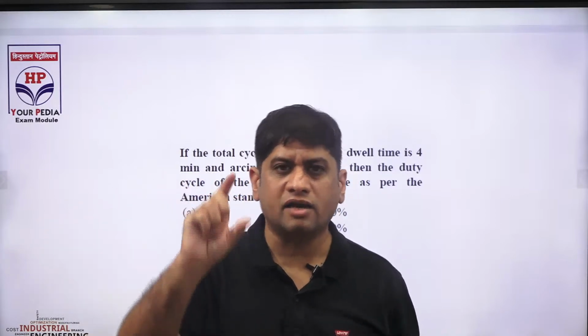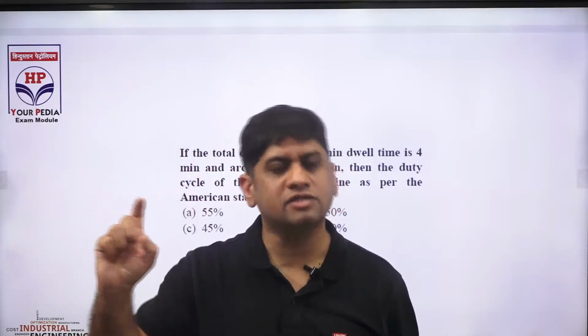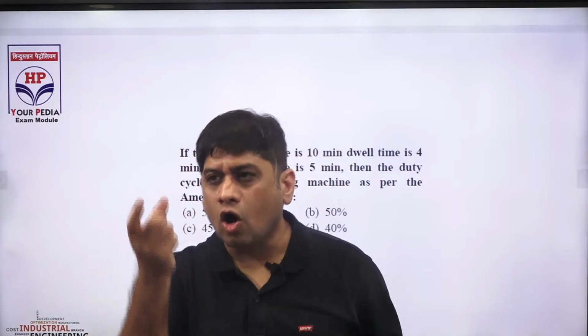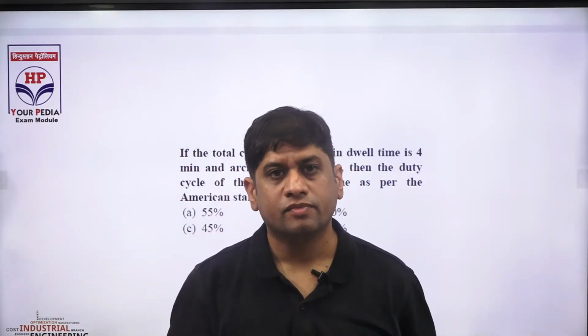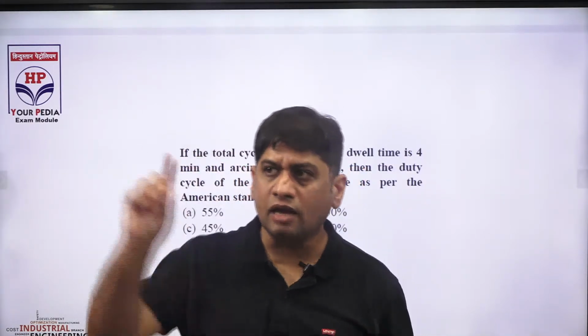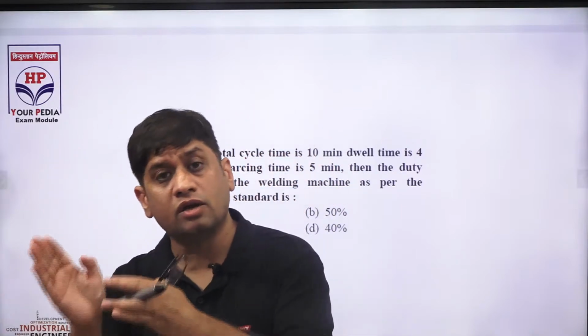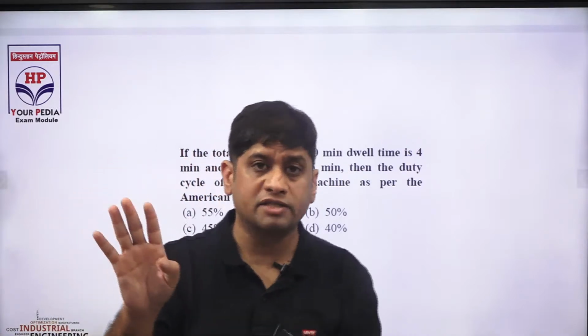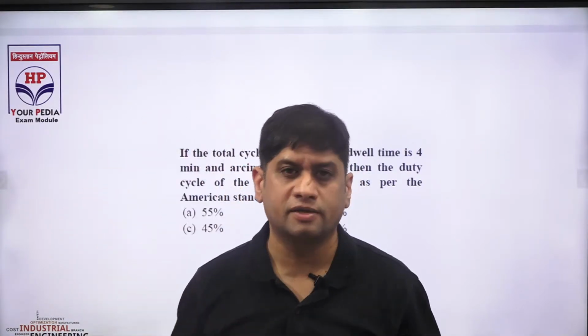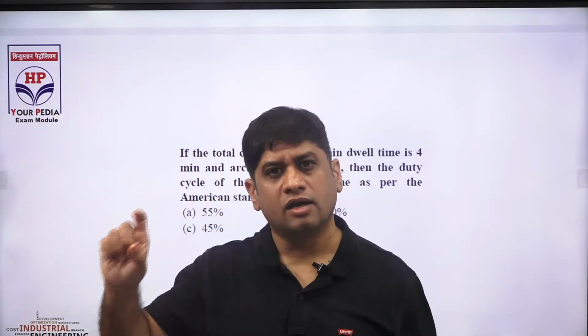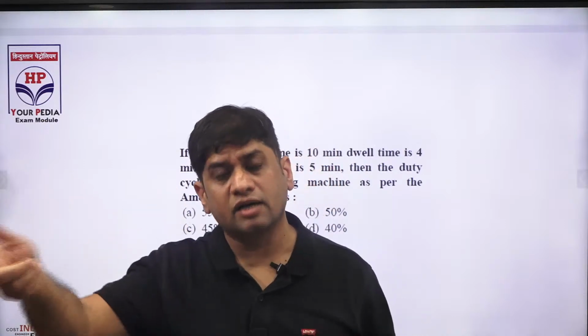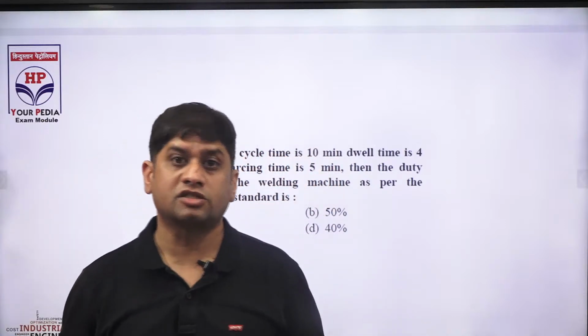They have taken a standard cycle, 10-minute cycle. In 10 minutes, how much time you are welding, that defines your duty cycle. In 10 minutes, if you're welding for 6 minutes and then you're giving rest to the machine for 4 minutes, then your duty cycle is 60%.